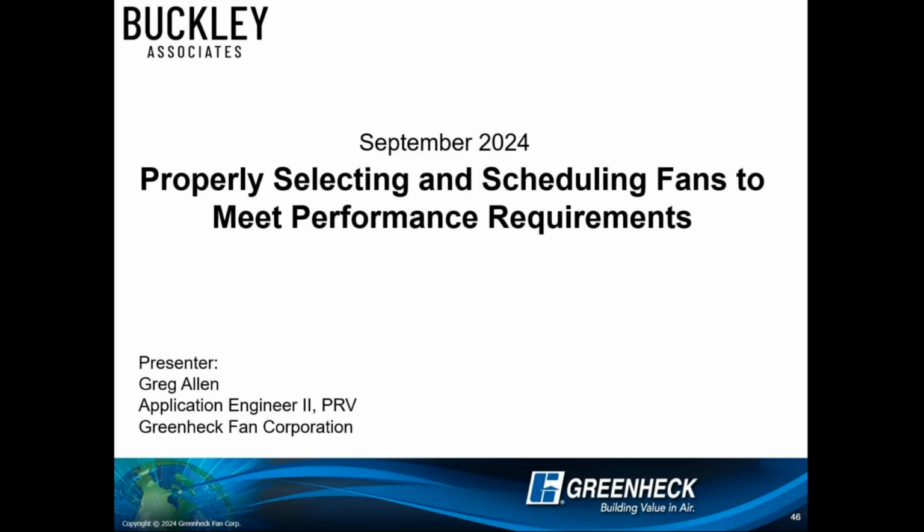That's solid. That's normal. And I'm recommending that you operate within that top percentage of what is capable. The numbers are pretty tight. You're not going to find many fans out there that are 98% efficient on moving air. So yeah, 60 would be normal for that type of construction across the industry.